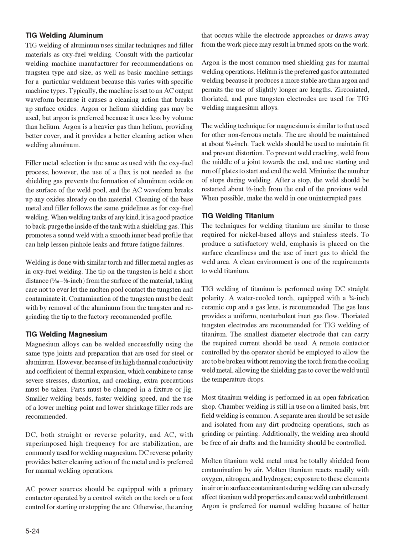Most titanium welding is performed in an open fabrication shop. Chamber welding is still in use on a limited basis, but field welding is common. A separate area should be set aside and isolated from any dirt-producing operations, such as grinding or painting. Additionally, the welding area should be free of air drafts and the humidity should be controlled. Molten titanium weld metal must be totally shielded from contamination by air.